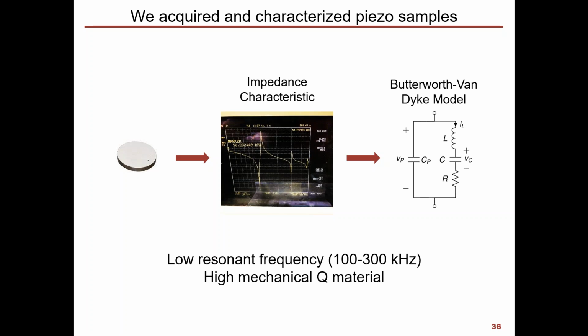Ramji Sharma asks, how do you maintain electrical contact when you have such a vibrating component? This is a picture of a disc piezo. Inside we have the PZT material, but on top, this entire surface is an electrode of silver that has been deposited onto the piezoelectric material. That silver is our electrical connection.